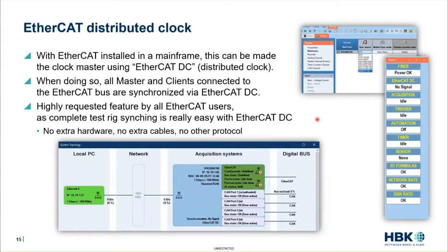As I mentioned at the beginning, this is one of the reasons you need that intermediate step. There are some pretty significant changes that happen within that portion of the firmware to support the distributed clock. So we needed 8.28 as an intermediate step to be able to transition between supporting distributed clock with 8.30 and supporting distributed clock with 8.26 and earlier. So no matter if you're going up or down with systems with EtherCAT, you're going to need to do that middle version of firmware.